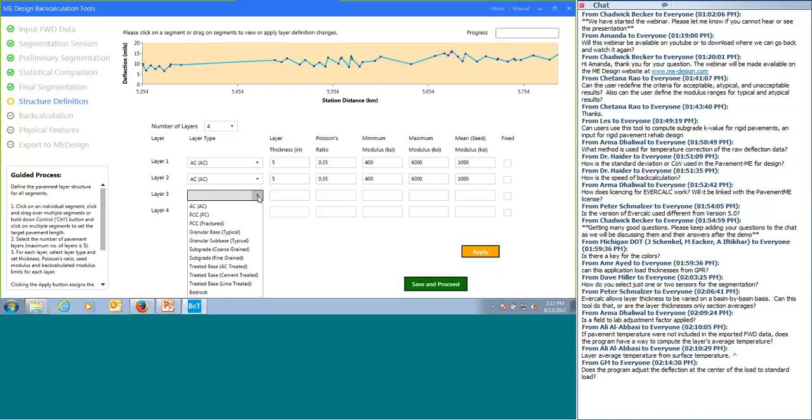The other item is that the 9 inches of aggregate base really wasn't what we would call good quality. It may have been infiltrated with some fines over the years, so this was defined as a granular kind of subbase or a coarse-grained subgrade material. So the 9-inch aggregate gravel base with the embankment that was there is now 27. So we've combined those 2 layers,